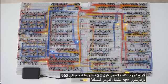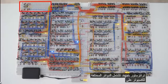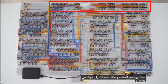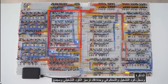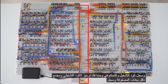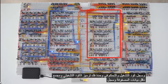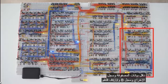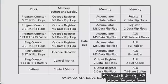The different circuits of the computer include the clock, program counter, ring counter, 10 bytes of memory, opcode register, opcode decoder, control matrix, data bus, accumulator register, output register, register B, and ALU. Let's run a quick example program and then talk about how each section of the computer is built.